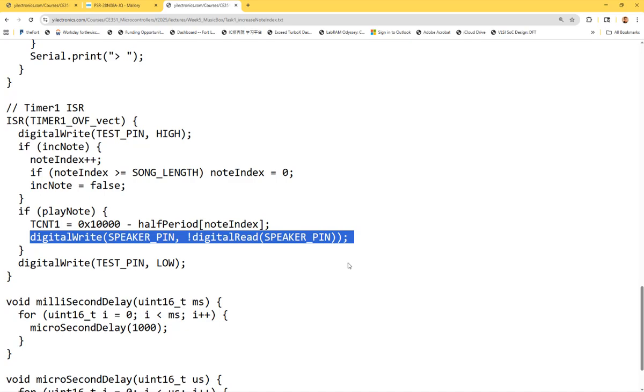Oh, that's an overkill. Just toggle a pin, right? Why? So you learn how to use ISR to toggle a pin. This is just a super fundamental example. But in the future, we have the music game. Then you have to use two interrupts to control that. One is for duration, one is for the note itself. It's getting more complicated, so you can find out why we have to use interrupts. There's no way I can control different tasks with just one simple loop. I have to interrupt it to do something else and come back. That's how that works.